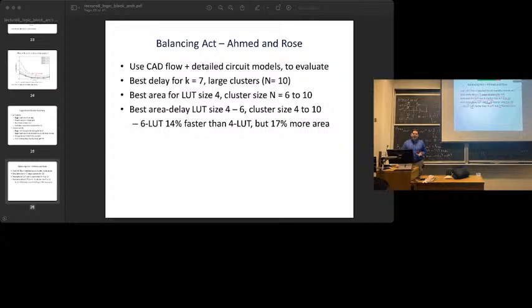So they're actually modeling, for commercial FPGAs, you make an FPGA family, you might make 7 or 10 variations, like a small one, a medium one, a big one, a really big one, 3 more I don't have names for. So when you're designing your circuits, you have to pick one of those. They're discrete, so you pick one that's going to be pretty full but not completely full. In architecture experiments, we usually don't do that.